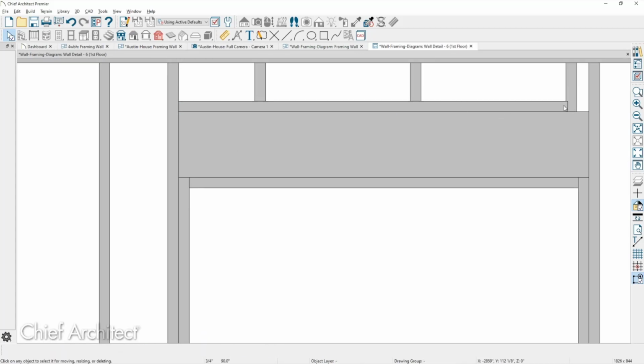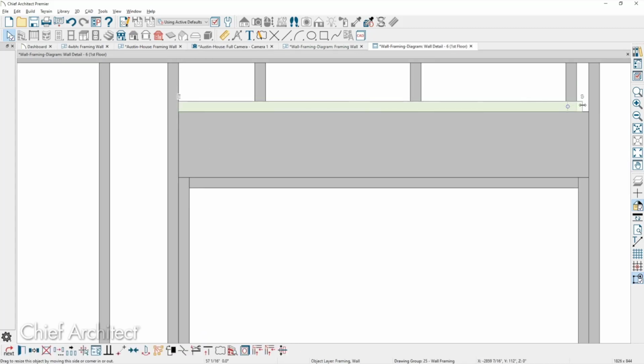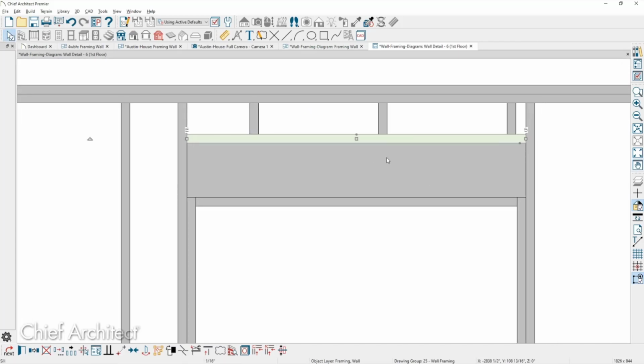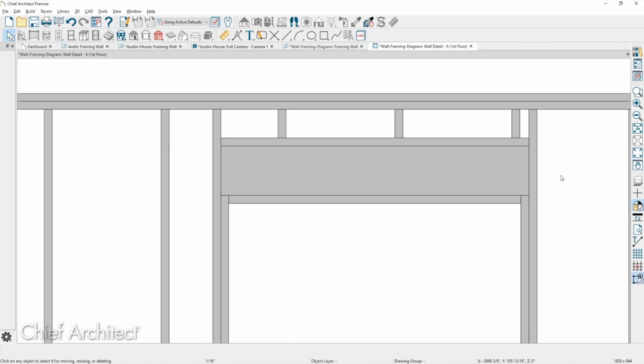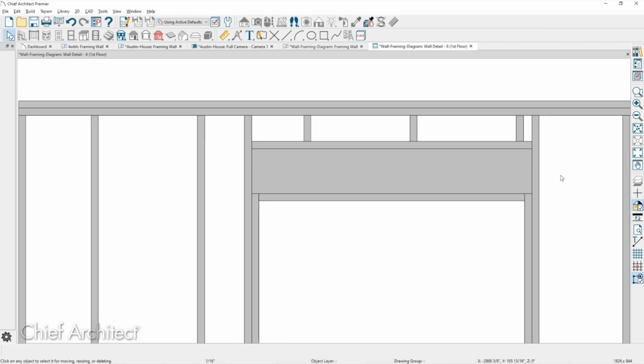So I pulled it over there, and then you can see that I still got a problem where I need to trim the other ones off, right? So now that the plate is selected, I'm going to use the trim command, and I'm just going to come in here and trim those off. And then you see as I click on each one of those, they've been trimmed off. Wow. Is that what you're after?